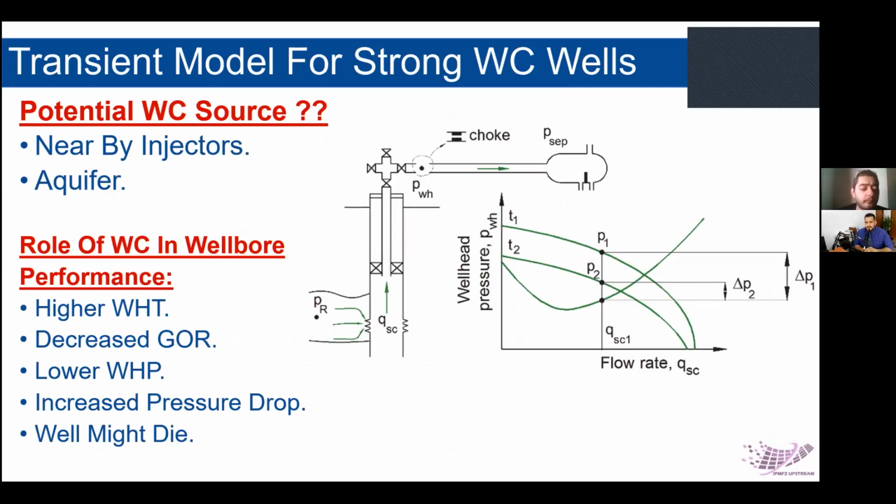So one of the issues we have in most of the fields, especially the fields that are undergoing water flood, is there is a rise of the water cut inside the well. However, whenever you do a well test, it takes something from 6 hours to 24 hours, and sometimes 48 hours, depending on the flow properties and the fluid and rock properties inside the reservoir.